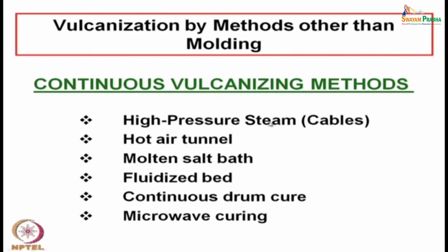During the residence time of that cable within the chamber, it starts curing and completes curing, then ultimately goes out of the tunnel. Then there can be a hot air tunnel, a molten salt bath, a fluidized bed, a continuous drum cure system, and also microwave curing. That means there can be a microwave chamber. If the product is introduced in that microwave chamber, that will cause curing or vulcanization.